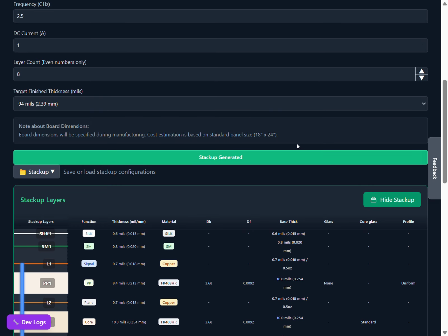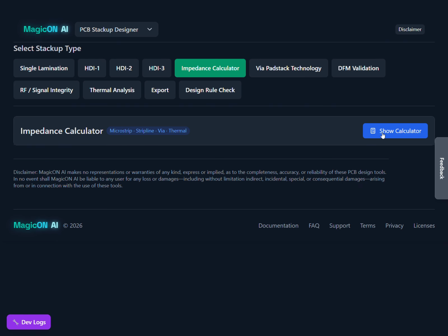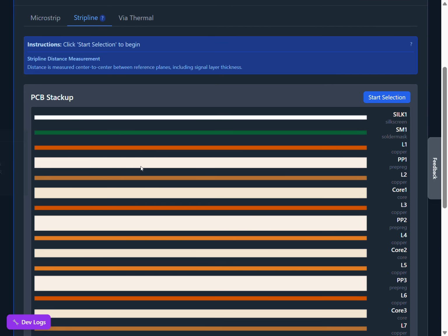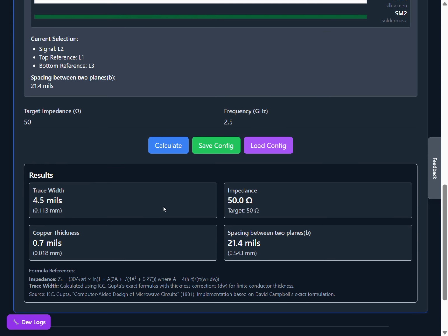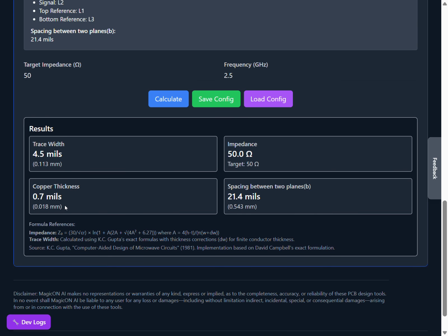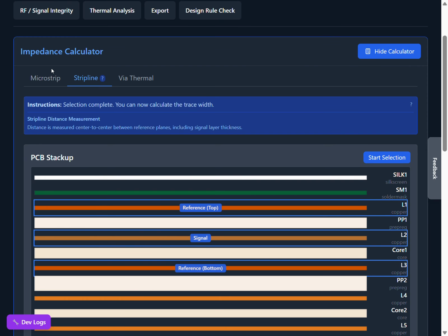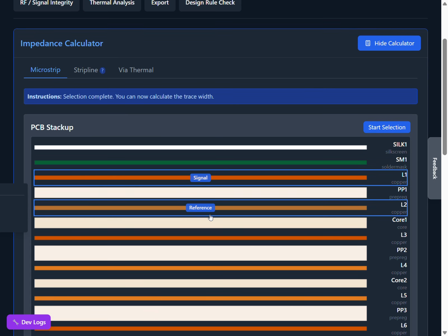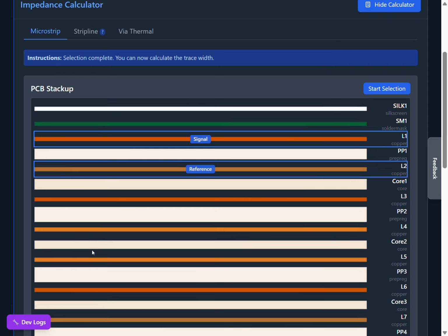Routing: microstrip is ideal for outer layers, antenna feeds, test points, or anything you need to probe or tune. Stripline is ideal for inner layers, dense multi-layer boards, sensitive analog, or high-speed digital where you don't want noise coupling in or out. On a four-layer board, outer microstrip is simple. If you want inner stripline, you need a signal, ground, signal, power pattern, or similar. The PCB stackup generator has a stripline inner primary goal that builds exactly that.